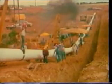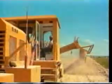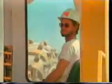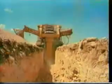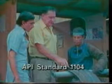The installation of a flow line requires careful supervision to ensure that the line is not damaged during handling, welding, or placement. Onshore flow lines are usually buried below ground level, typically 12 to 36 inches, for safety and logistic reasons. The standards concerning welding methods as well as testing procedures are outlined in API Standard 1104, Standards for Welding Pipeline and Related Facilities.